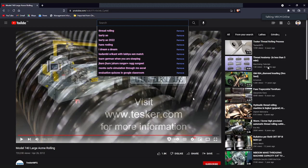Oil-based cutting fluid is provided where the need for lubrication is more, because there will be a lot of interaction between the thread rolls and the workpiece, so you need a lot of lubrication. So oil-based cutting fluid is used very specifically here. But in heavy machining where a lot of temperature is generated, water-based cutting fluids are used. The reason is that the heat capacity of water is great. Okay, sir. Is it clear?